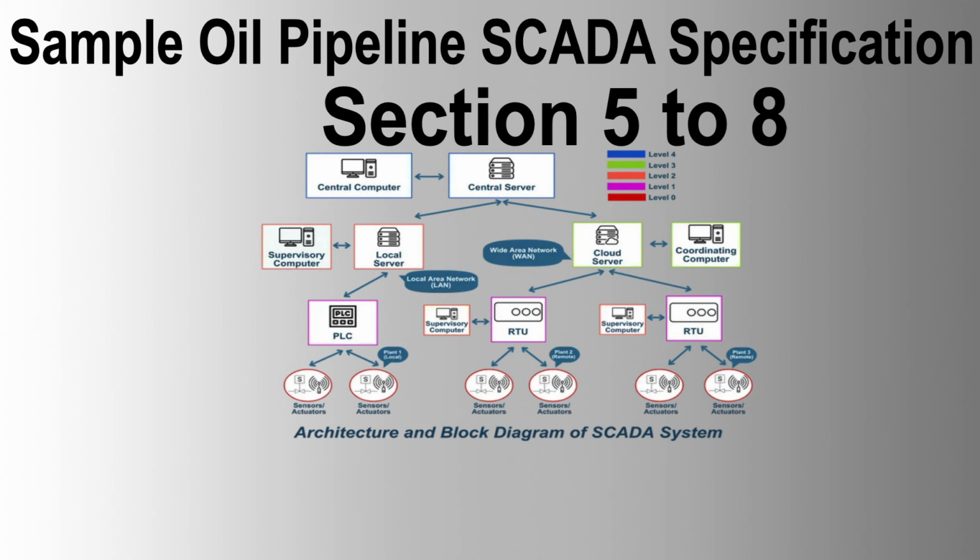6.3.5 Power Supply and Distribution. Electrical equipment shall be suitable for 110-volt AC 50 Hz single-phase power supply from a UPS. Redundant feeders shall be supplied to each panel, each capable of taking the full load of the system. The system shall include isolation transformers to prevent electrical noise interference. Power distribution cabinets will provide 20% spare feeders of each rating, with an additional 10% spare space for future requirements. All power supply units shall be monitored for faults by hardwiring into the system as digital inputs.